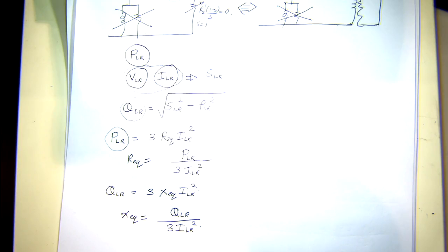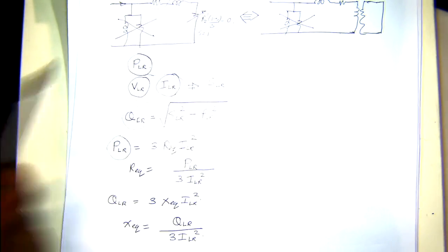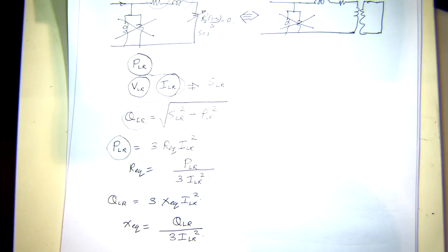The other test is when you bring the speed up close to synchronous speed, we'll have S close to 0. So that's like the open circuit test. But one of the complications is that if you powered up the induction machine and haven't connected any load to the shaft, it will spin close to synchronous speed, but then you'll have rotational losses. So if you run it under no load, then you have rotational losses plus the core losses as well. So that's a complication.